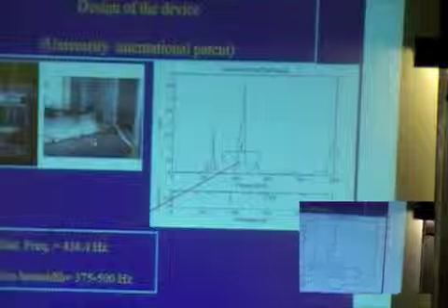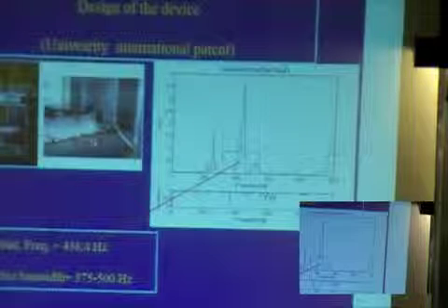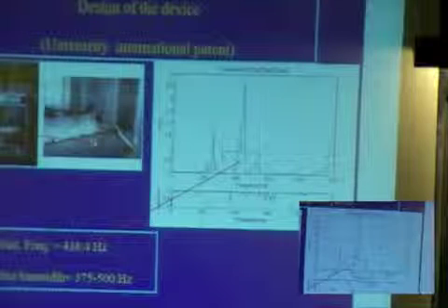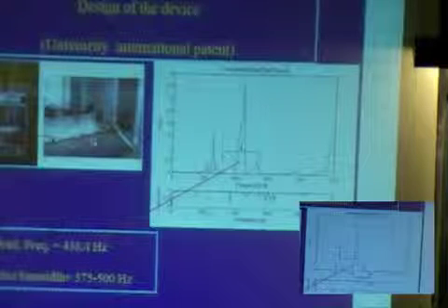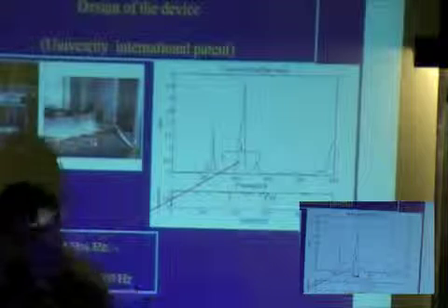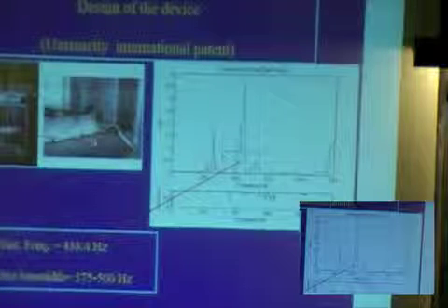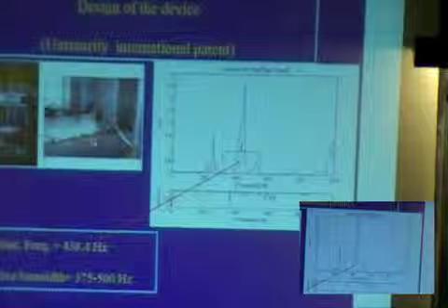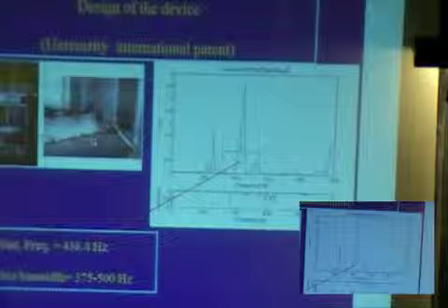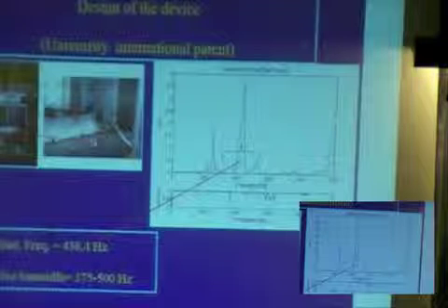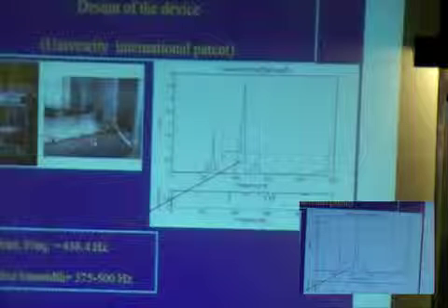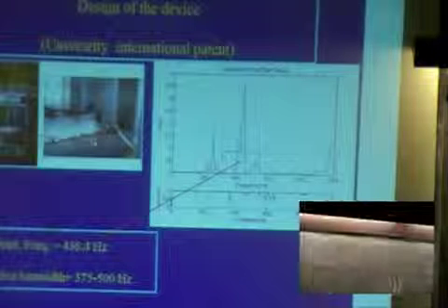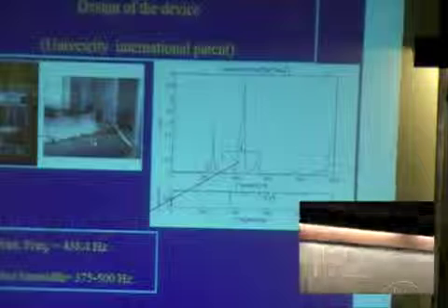This is the clearest peak in the frequency response function of your system. Say that this peak in the response is particularly difficult for the electronic package. Suppose that at the moment of launch you have the spectrum of the response of the plate to which your electronic package is attached.